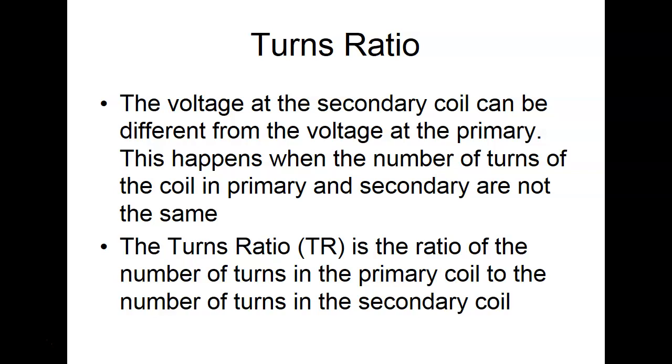And you can either hook it up, step up, or step down. That all depends on the transformer. Some you have to be real careful with, because the insulation on the core might not work to make a transformer that's normally used as a step down and use it to step up. You understand what we're saying? So if I use what we used to call the secondary as my primary, and then use my secondary as what was originally the primary, it will step both together. Some transformers allow you to do that.